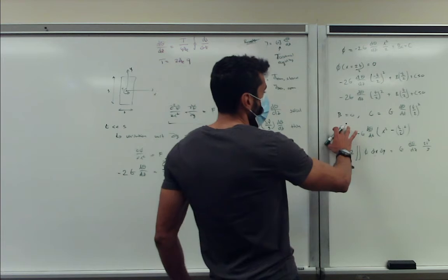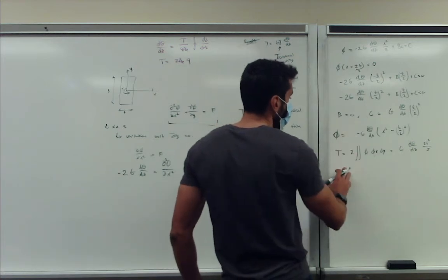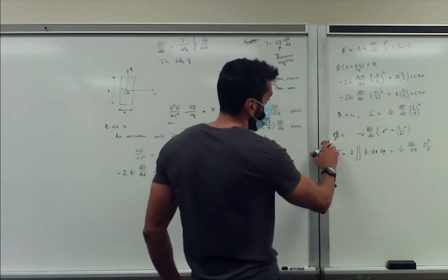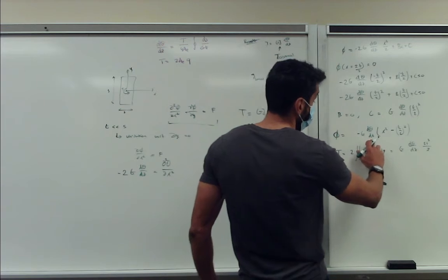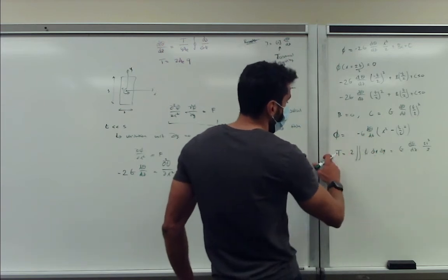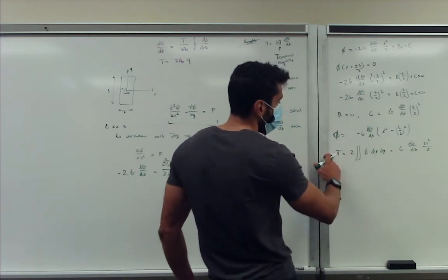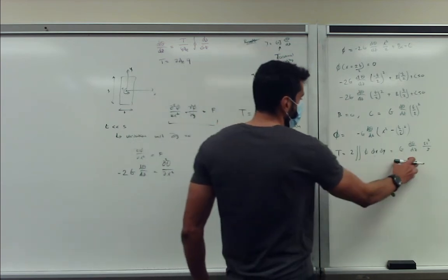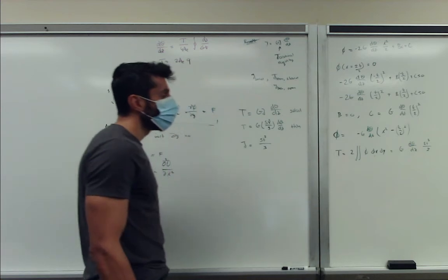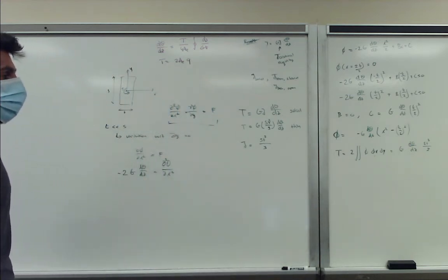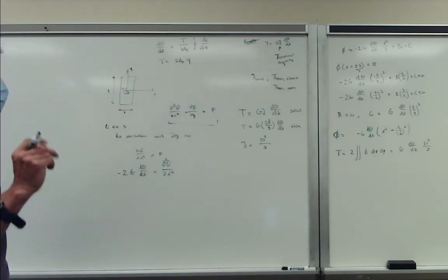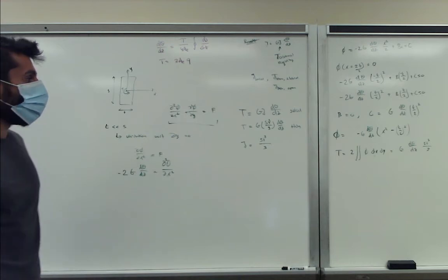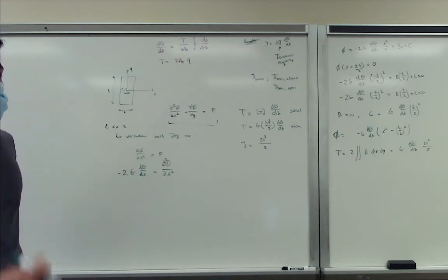So we did our integrations and came up with a new equation for our stress function. Previously we knew that our torsion must be equal to our stress function integrated over dx dy. So we did that, and came up with a new equation for the torsion of a narrow strip, which we call a thin wall.